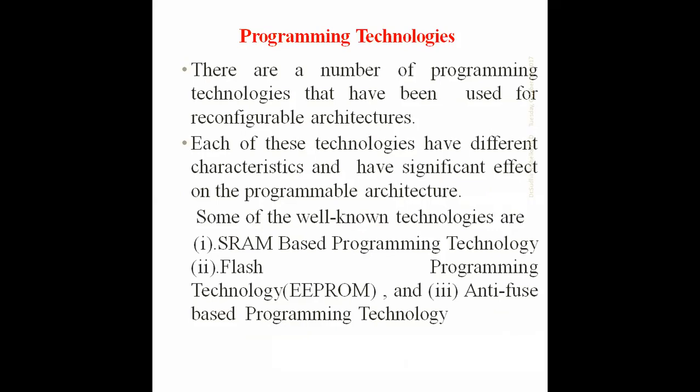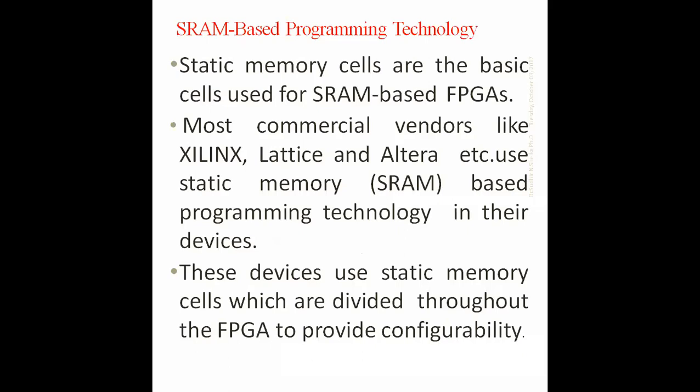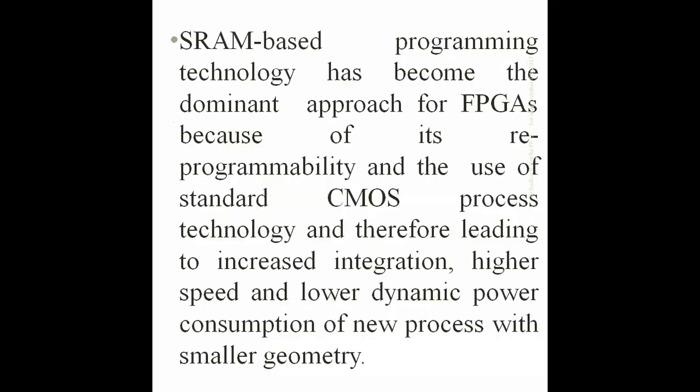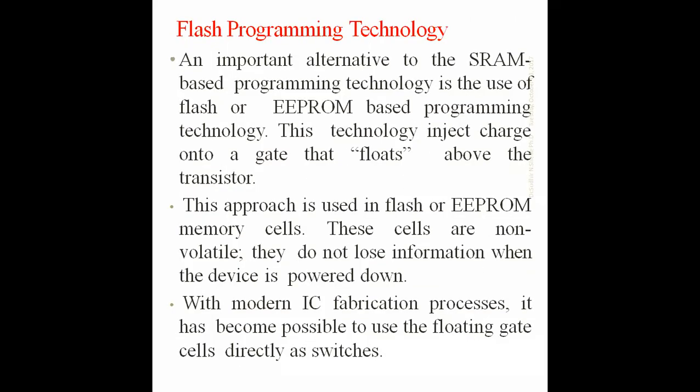What are the programming technologies? Already I explained two things: SRAM and flash programming, and anti-fuse. You may go into detail on what is static RAM based programming technology, flash programming technology, which is EEPROM, and anti-fuse based programming technology. What is meant by the static RAM cell? What are the different terms used in that?